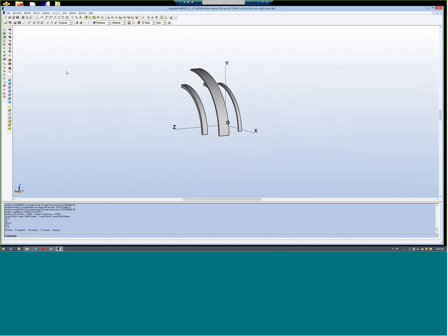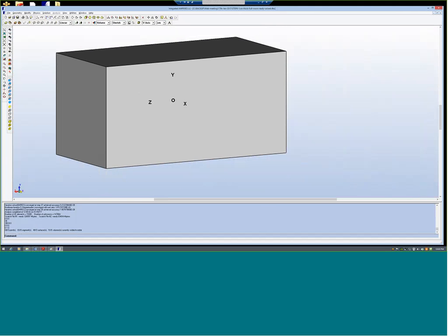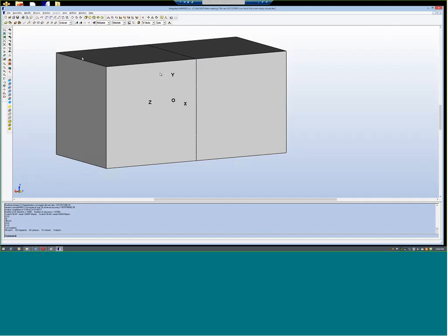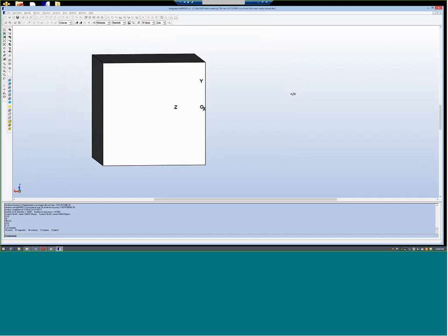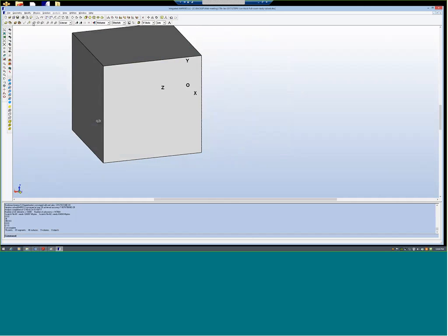In a similar way, you have to do this for this box also. Okay, geometry, first intersection, cut the geometry with the z is equal to 0 plane. Cut it. Okay. So once it's cut, modify, delete volume, delete this, because your problem has to be defined only at z greater than or equal to 0. Okay, done. Only half you got.